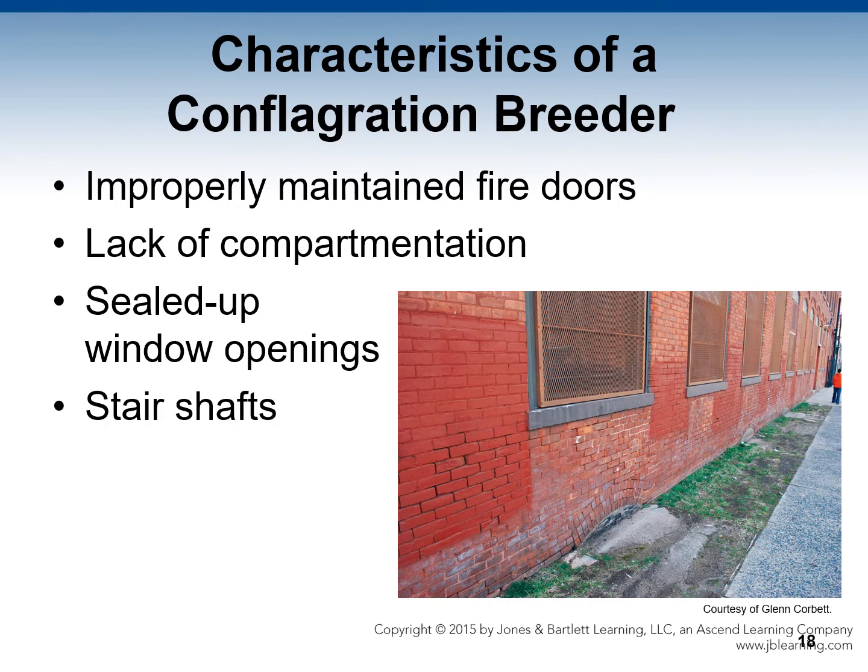Improperly maintained fire doors and lack of compartmentation is a frequent problem, and sometimes you have sealed up window openings, and stair shafts may be an area of refuge for firefighters depending on how they're made and how they are protected from fire, like with cement block or something like that.